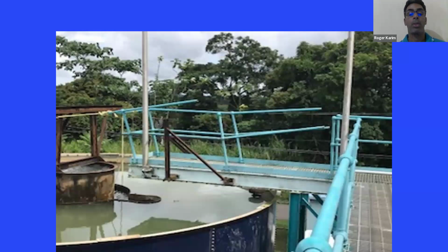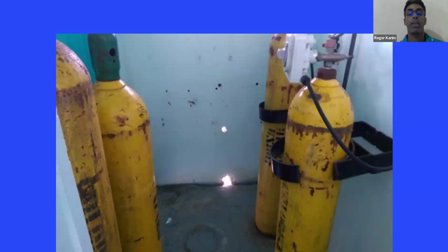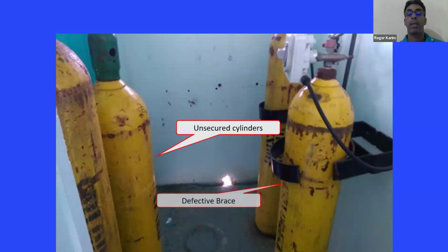This is a wastewater treatment plant. No, water treatment plant. It's a cone clarifier. And you can see the broken handrails over a large body of water. So you have the access gangway, but the guardrails are in very, very bad condition. Well, chlorine cylinders, unsecured. Defective, the brace is broken, so it's not really secured. Tripping hazard here.